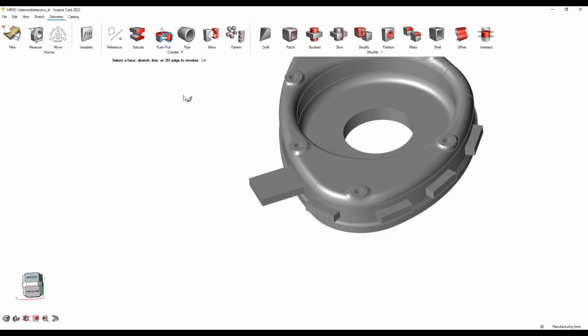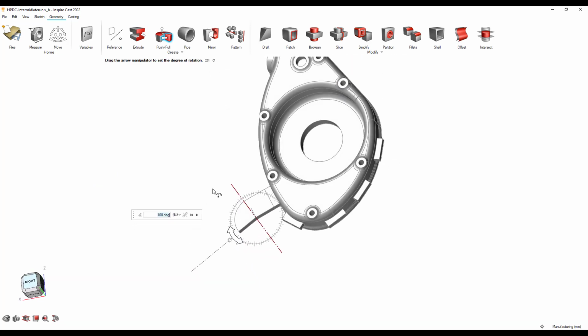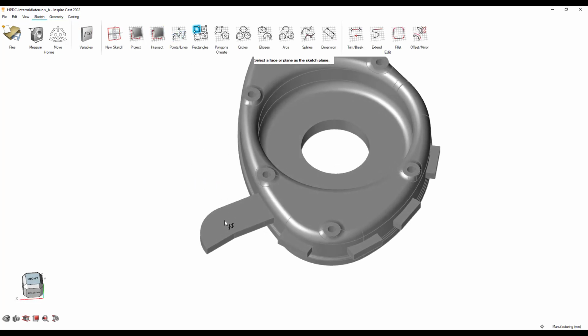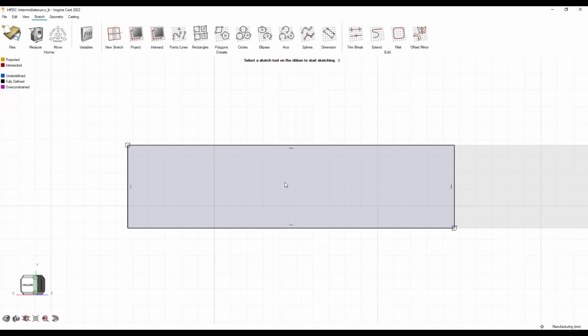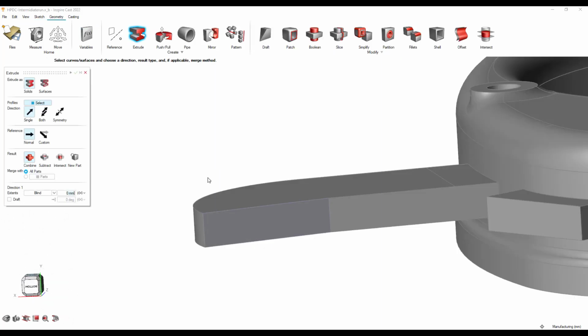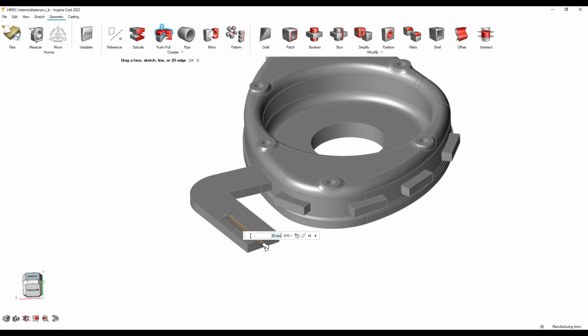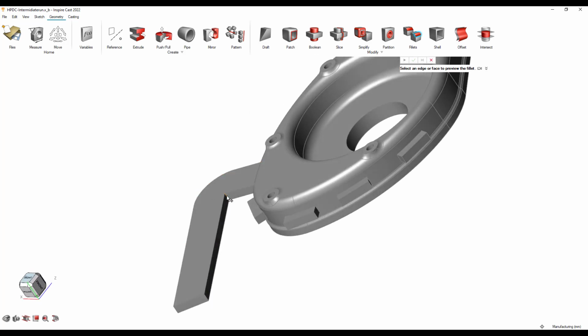sketching, and then I can also use the revolve tool to revolve the surface. Moving forward, back and forth, creating sketches and creating extrudes from the sketches, I can eventually get the runner design ready for my final simulation. So as you can see on your screen, just like the one gate where I have created the initial filling system, I can do a similar thing for the rest of the 4 sections and merge them together into one location.